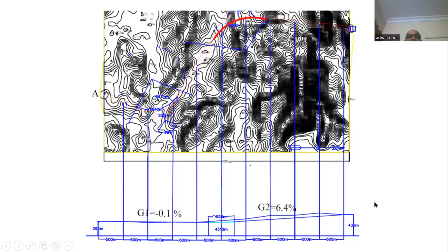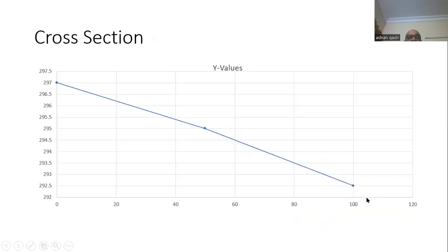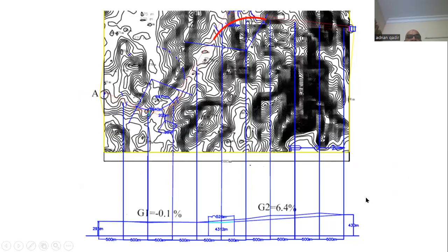This is how we draw our elevation, and you can see from this drawing, once we have drawn this profile, the above one is what we call the ground level, and on that I've drawn my finished road level in this manner, because we all know that in order to have a better vertical alignment, we have to balance the cut and fill.